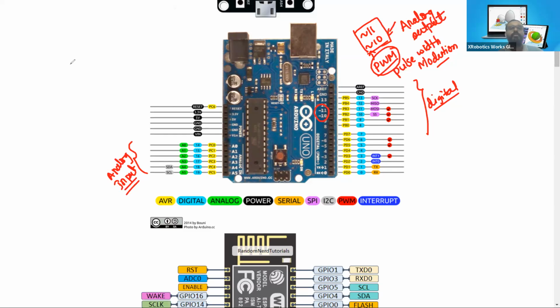We understood two terms while utilizing the analog and digital systems in our last class: the analog system requires a range, even to take the inputs and also to produce the output. And suppose we are controlling a car using programming, then we should control the speed of the car using the analog function, the analogWrite command. The analogWrite command will work on PWM pins, and you should take care of this while programming.